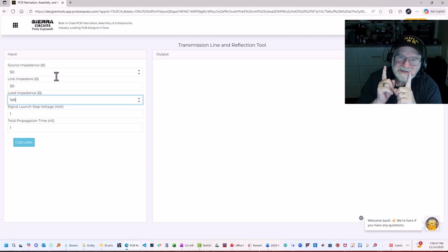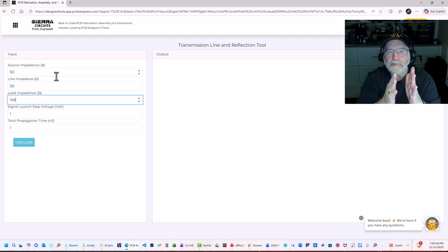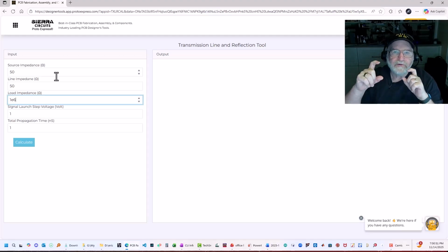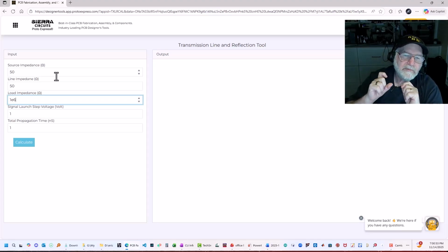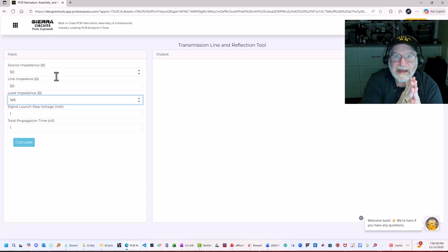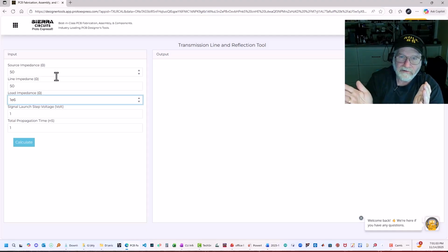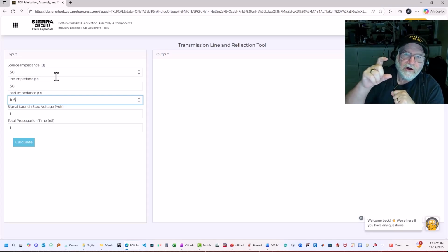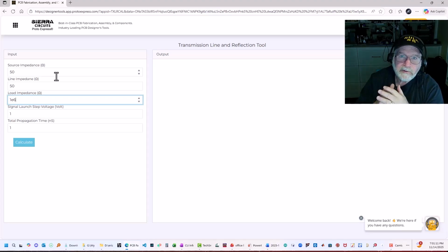So remember, keep separate the signal that propagates and the voltage that the scope is going to measure. The signal is effectively a vector. It has voltage magnitude and direction, propagating in either left to right or right to left directions, but the voltage that we measure on the nodes at the far end or at the source, what the scope would measure, is a scalar, has no information about direction.